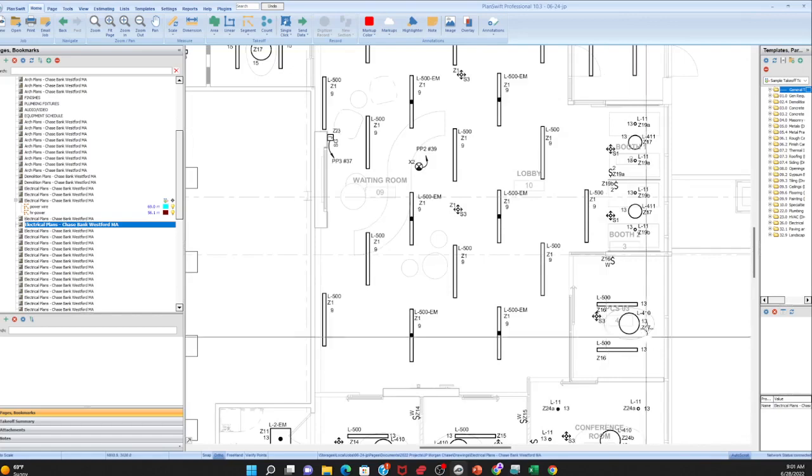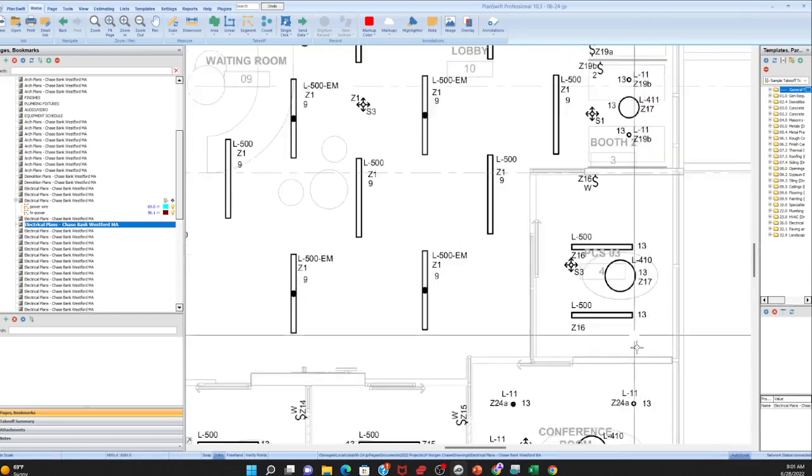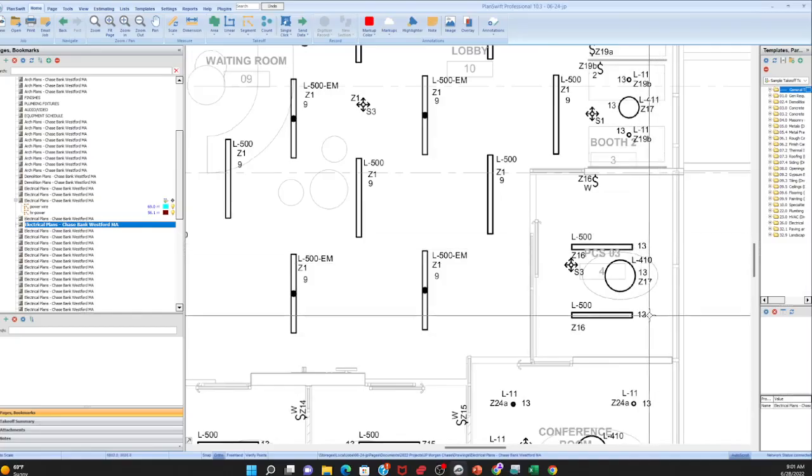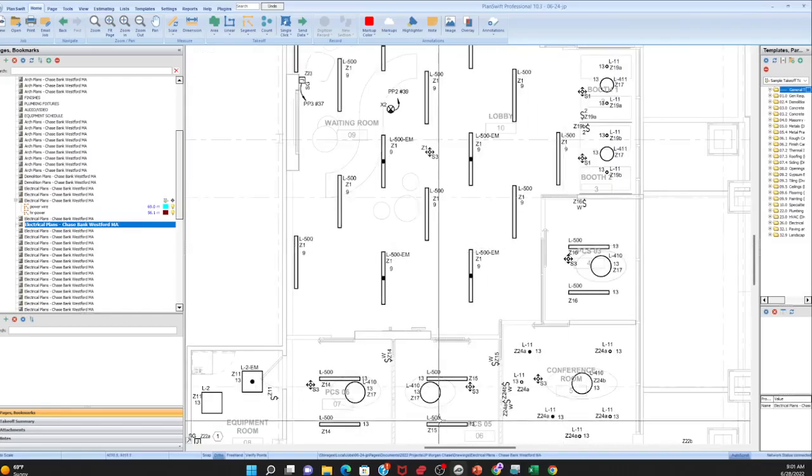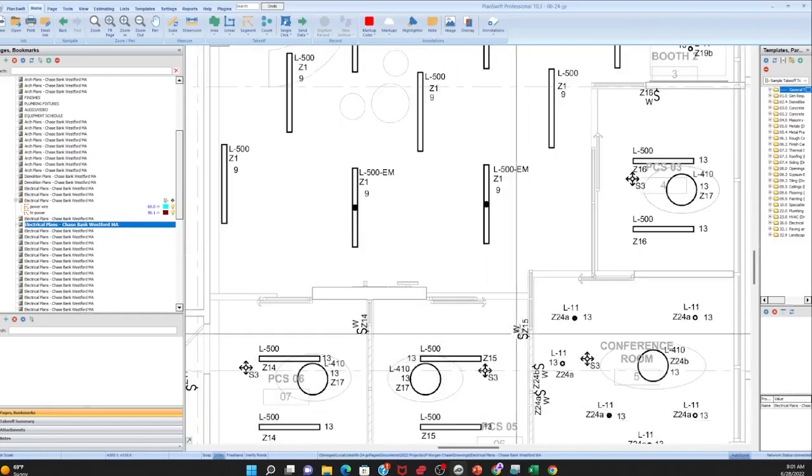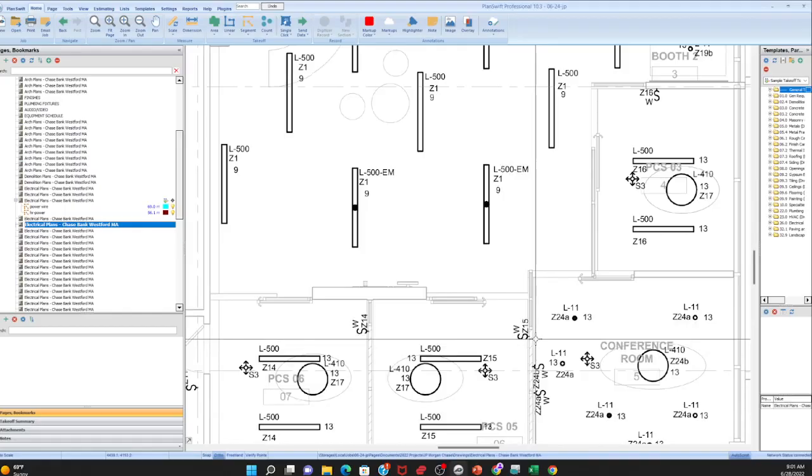the lighting. You're trying to account for any wire that needs to be connected to these lights. These are all 13s, so these are all going to be connected together. Okay, all the 13s. And then look, the switch. At this point too, when you're doing those counts, one of them in the row or the daisy chain has to go back to the next. Right, exactly. It's got to go to wherever.